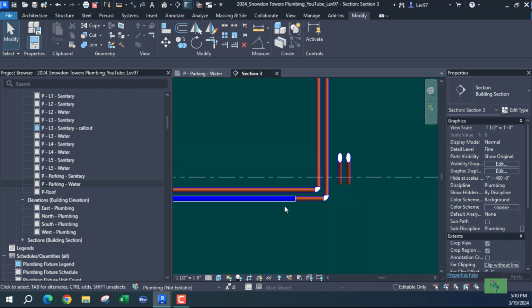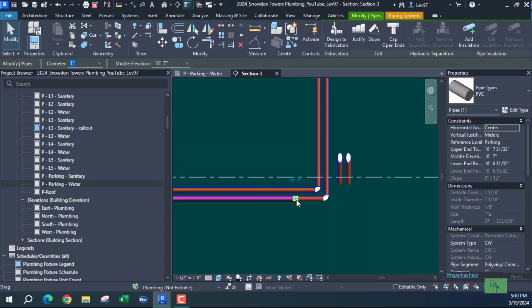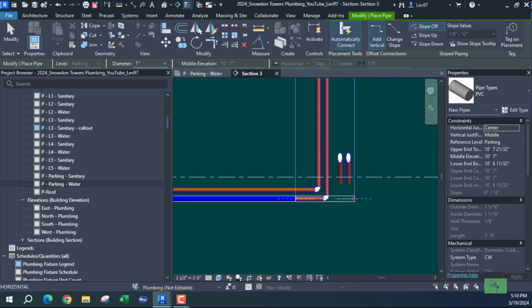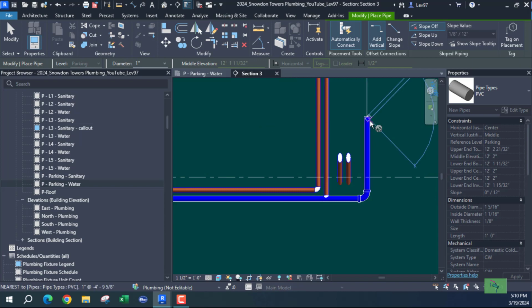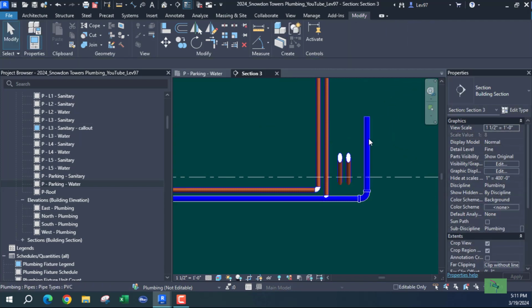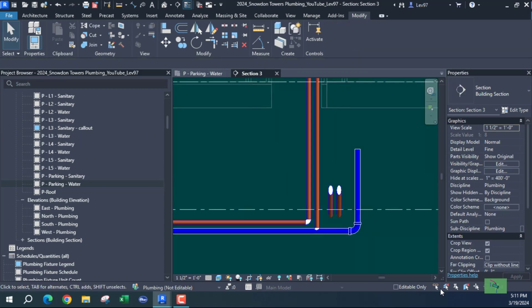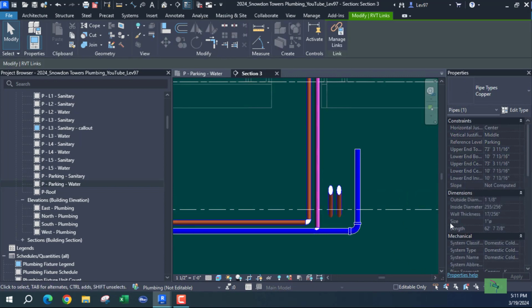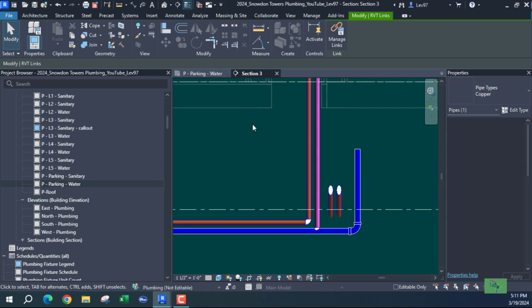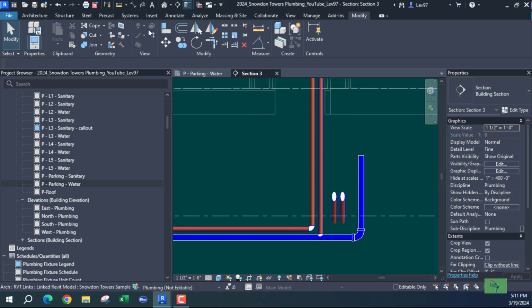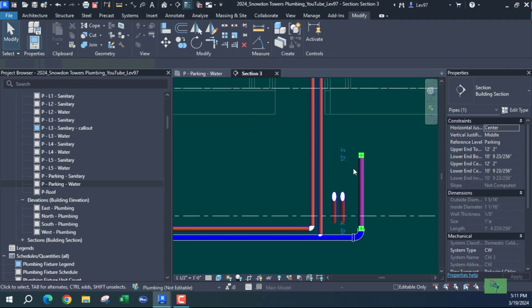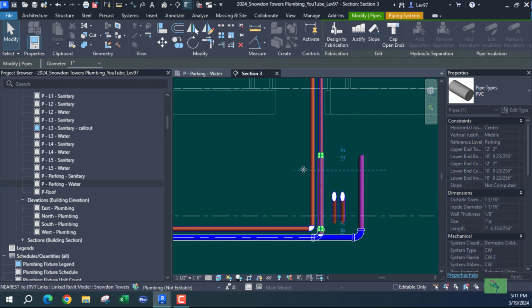So you can see that what I need to do is go over. I'm going to overshoot and come back. Oh, I think these are 1 inch size. What size? Yeah, okay. So you can check the 1 inch. You can check your linked models by hovering over and pressing tab, okay? And it's telling me that the size of the link model is 1 inch, which is what I'm using. And what I should be able to align, can I align? No, I'm not going to try that. Okay, so let's go over and just put that guy right there.